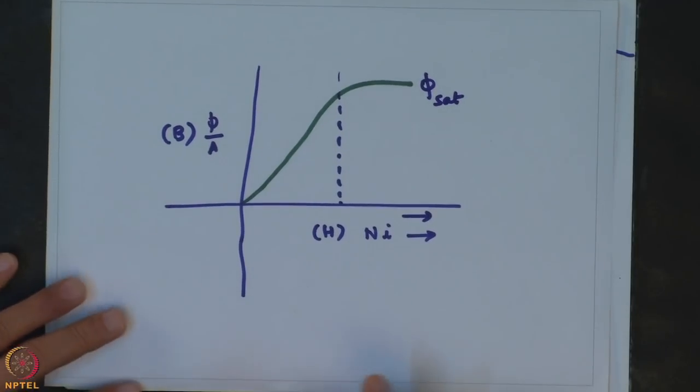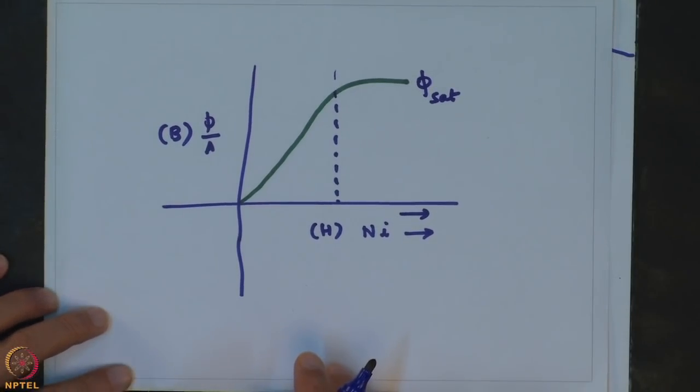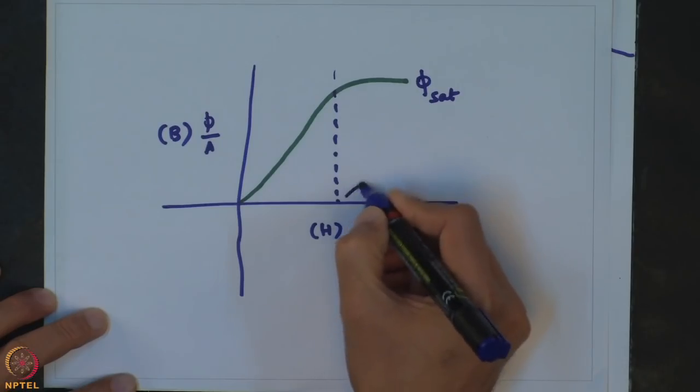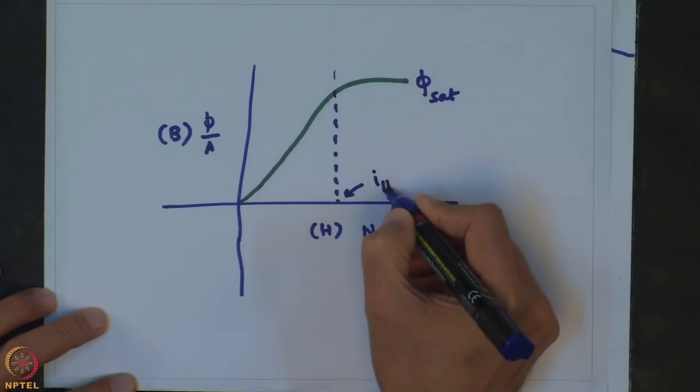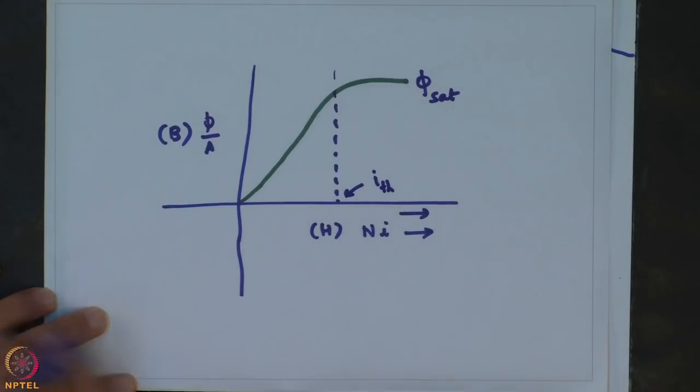It is important that whenever we are dealing with a magnetic system, we do not operate our system at currents more than a threshold value. So, if I call this threshold value ITH, my current should not exceed ITH to avoid saturation of the core. Saturation of the core leads to the shorting of the electromagnetic system, and it actually will draw a large amount of current, which might cause other safety issues with the equipment or with the circuit.